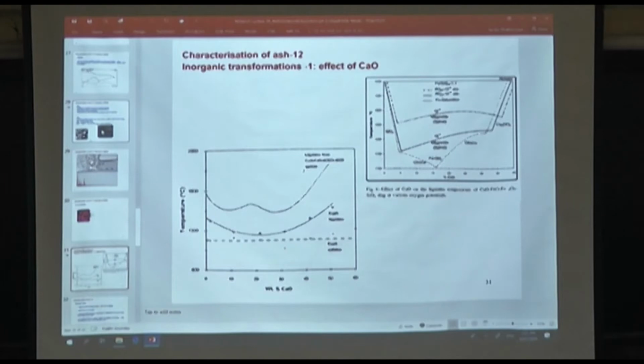So what does that mean to the researcher or to the plant operator? It basically tells you that we really need to be very, very careful when dealing with this particular coal, when that has a lot of calcium or less calcium, or a lot of sodium, iron, etc. If that is there, then the best thing is to find out what is the safest temperature zone to operate and what temperature zone to avoid. And that's what the engineers eventually will need to know.